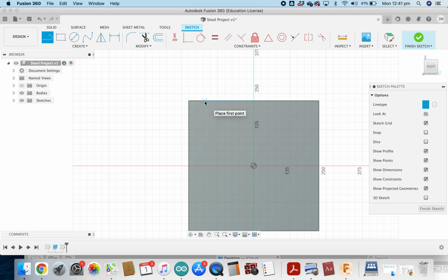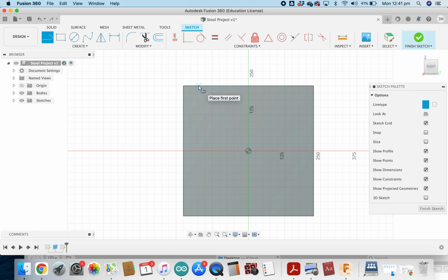So what we're going to do really quickly is just draw 3 construction lines running down our page, and we want them to be parallel, but we're not really concerned about where they sit at the present. You can see these lines are orange. If your tool does something like this, it's quite simple. You can just press Escape and that will leave the line tool, and then you can press L for line and it will bring it back up for you.